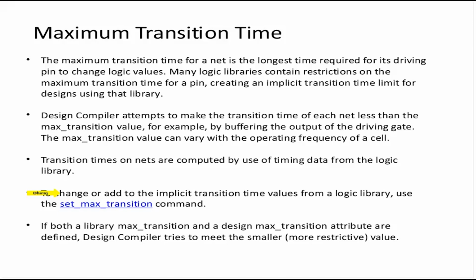When you start doing synthesis, I would recommend not to use the set max transition command. It is used for very specific cases where you know that you want very good transition on some part of the design. Only in that case it is used.